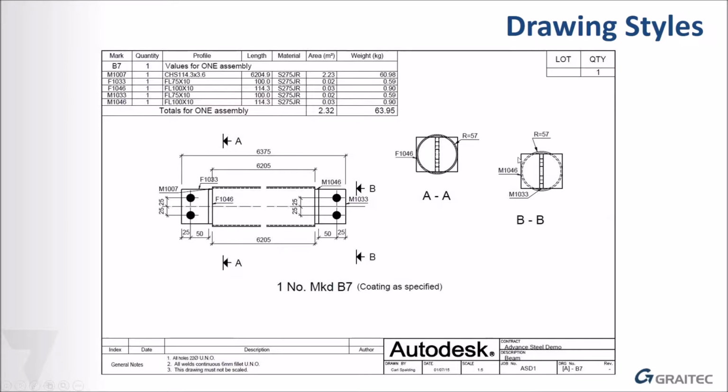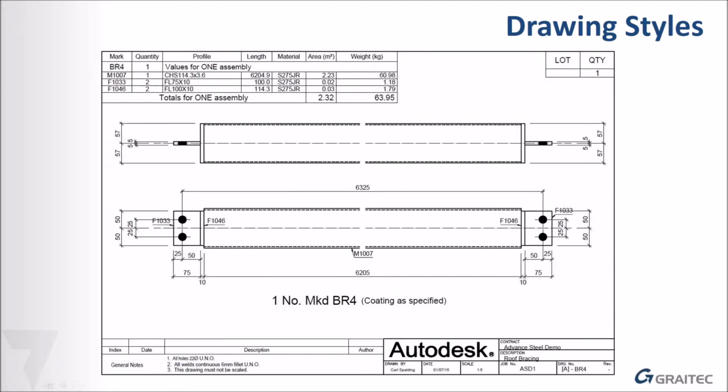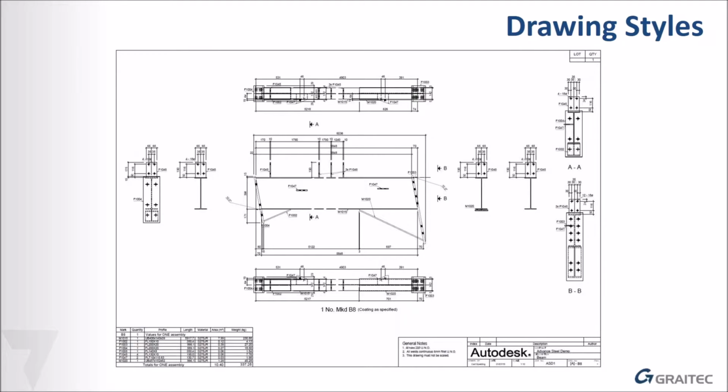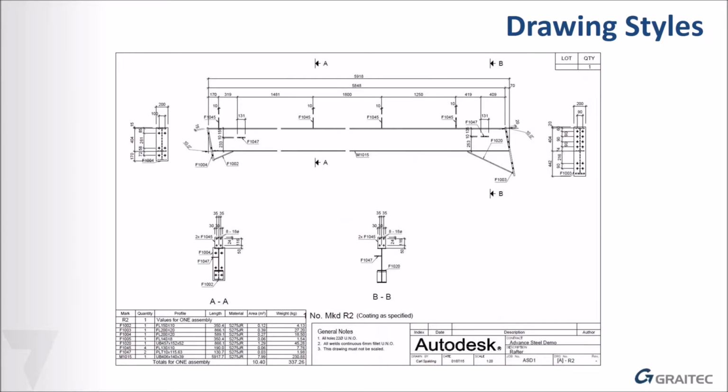So that is what it ran automatically, which as a detailer is not very good. When we changed the model role to roof bracing, it triggered a different drawing, which gave different labeling and dimensioning strategies. So the only thing that we've changed from that to that is the model roles in the model. This is a rafter drawing with the model role beam, and these have just been called plate and beam, so they've not used the correct model roles. We corrected the model and ran it automatically, and that's the difference.